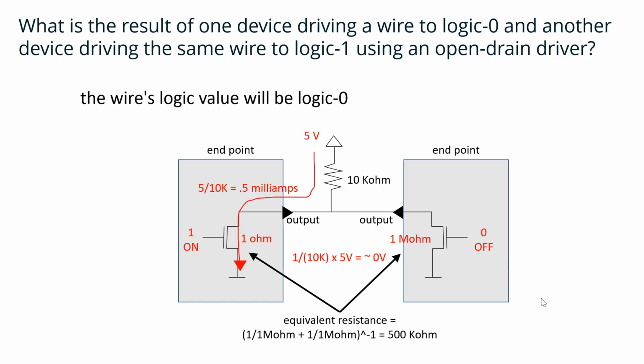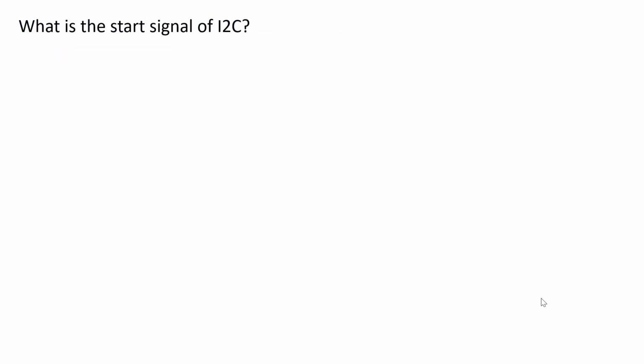Generally, I don't have a lot of experience with this. But my understanding is that if you do that, you'll get a voltage that's somewhere in between 0 and 1 in the forbidden zone. And then if you read that value, I think it'll probably read as a 1 because it'll be above 700 millivolts, which is the typical threshold for a transistor. So the forbidden zone I think will be read as 1, but it's not a good idea to try that.